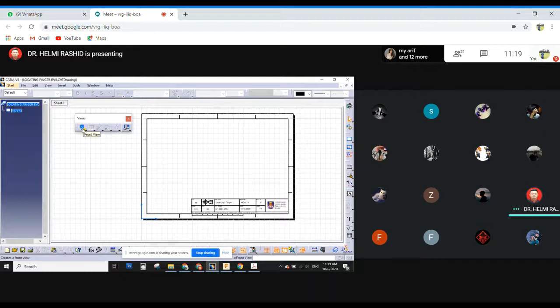When we have third angle projection, or first angle projection, your front view will be what we call the parent view. The parent view means that if you move the parent view, the projected side, top, bottom, or right side views will follow it. I'll show you after this. Others are not activated yet. This is the unfolded view. So the first thing is we need to include the front view.